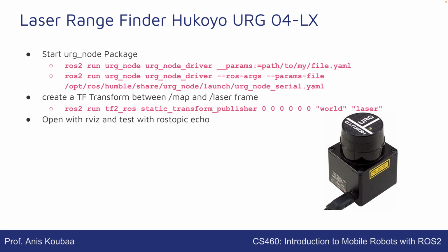It's this path. When you install the driver, you're going to have a launch file that will contain the configuration of the laser scanner. By default, it's going to connect on the USB port, on a certain port called ttyACM0. It can change, and we can change it also in the configuration file, as I'm going to demonstrate in a few moments. And this is optional, but it's if you want to visualize in RViz.